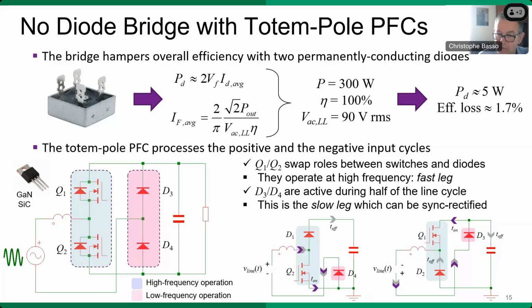In this type of circuit, it's very important to decode the line polarity and drive the active parts accordingly. The TP PFC structure has been known since the 90s, but has only become popular recently owing to the introduction of wide bandgap transistors, featuring zero or low switching losses when recovering from conduction in the third quadrant.